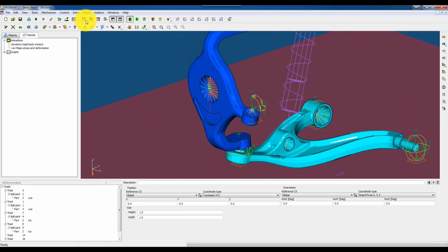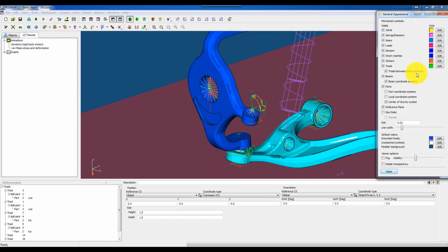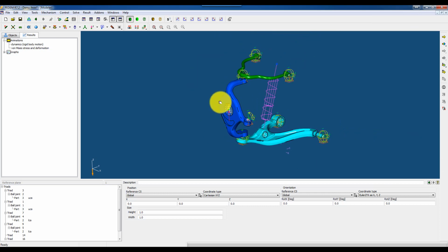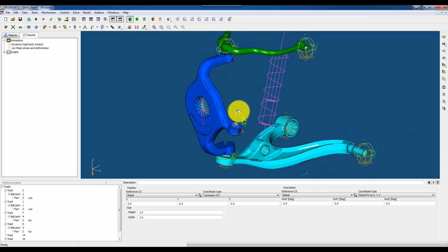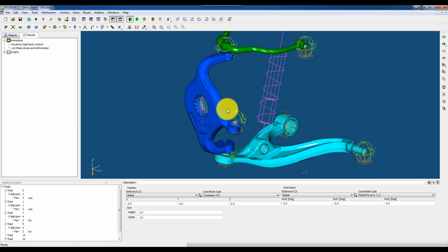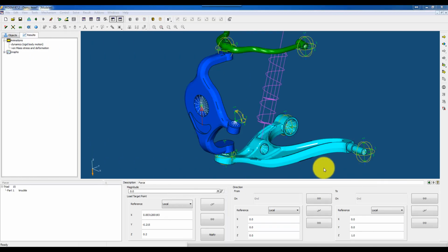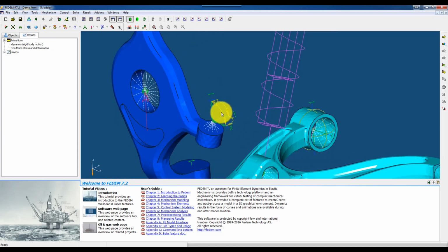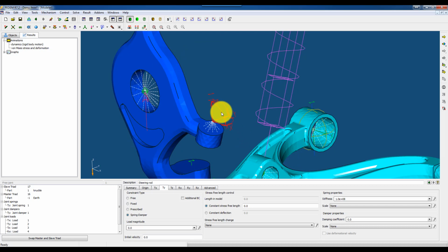Okay, after removing the reference plane, I have removed the singularity. And then I can run once more. Then I used a free joint to model the steering rod, and I've applied a stiffness, but perhaps we should apply a motion as well, a steering signal.